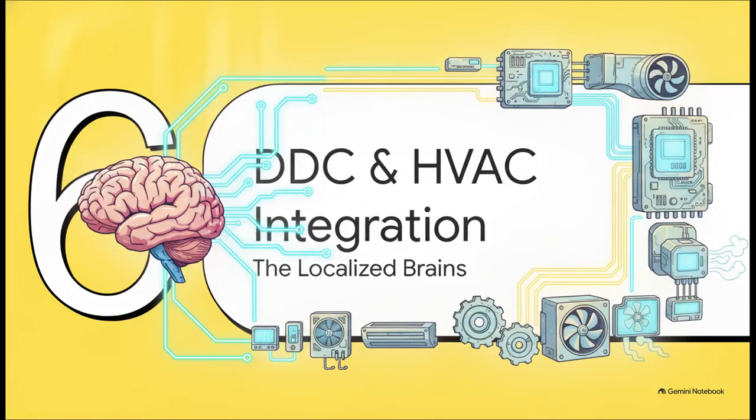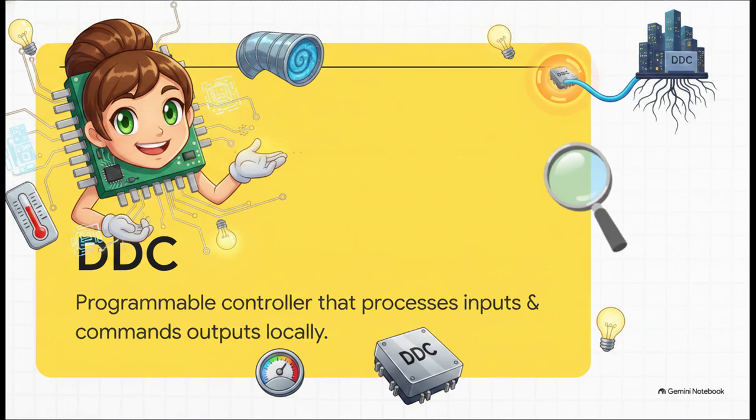Moving on to our final section, number 6. DDC and HVAC integration, the localized brains. DDC stands for Direct Digital Control, and honestly, these little guys deserve their own spotlight. A DDC is essentially a small, rugged computer sitting inside a metal control panel right next to the equipment on the floor. It reads those field inputs, runs its programmed logic, and commands the outputs.